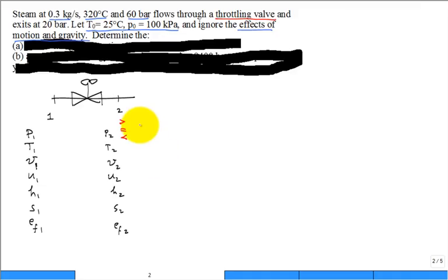You see my kind of question, how I'm phrasing that? What does the pressure do? It drops. With confidence, or they need to tell me in the problem statement? They're confirming it when you look at the value here, 60 bar and 20 bar. It's confirming it, but man, if it didn't drop, I've got a bad throttling problem. It's going to drop.